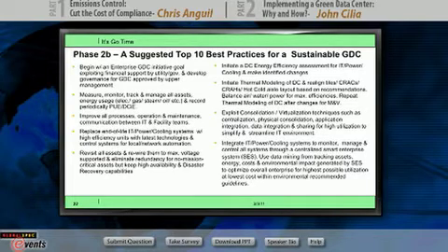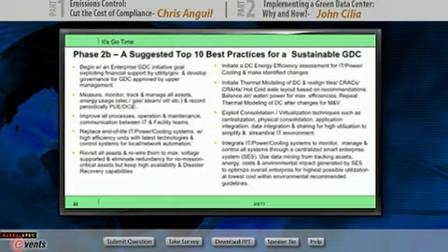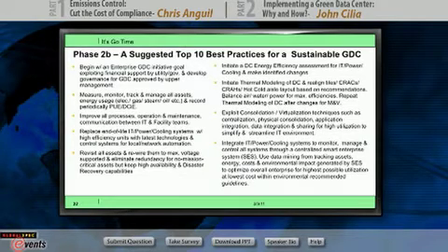Make sure that you verify, and you can go back over all the equipment, to make sure that the power connections to your equipment are based on the highest voltage that the system can support to save you energy. As well, if you have some non-critical systems with, for example, a dual power supply, you may want to disconnect one of them in non-mission critical systems. That's something to look at sometime.